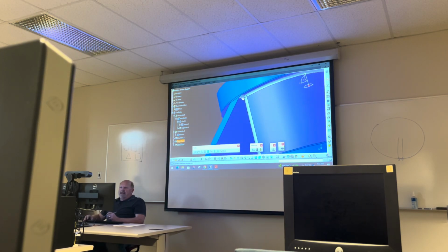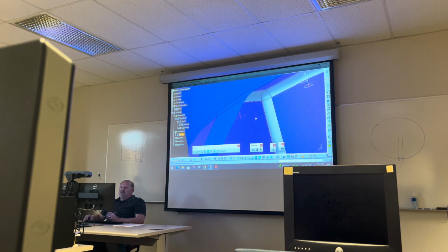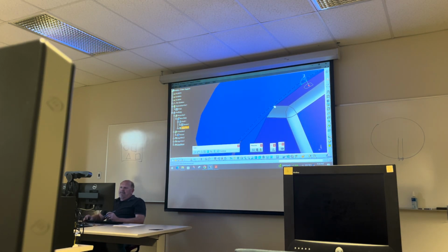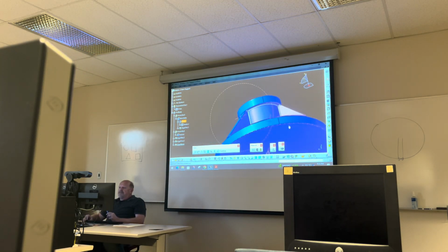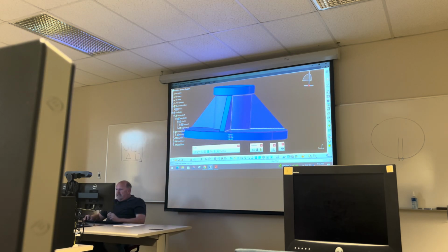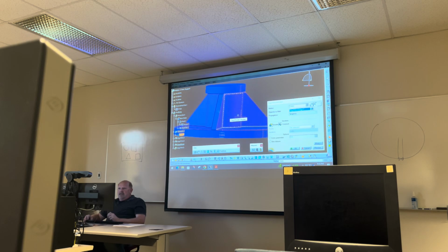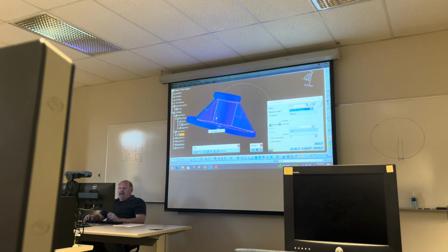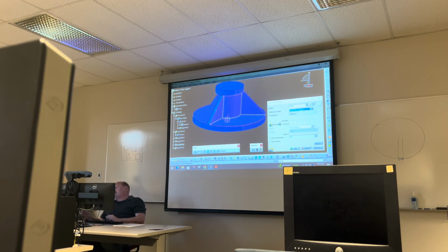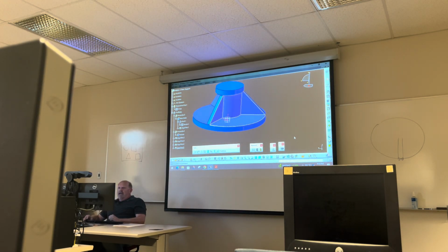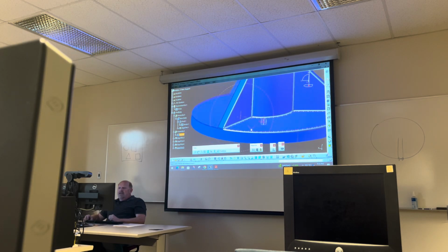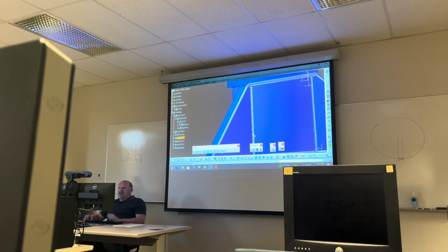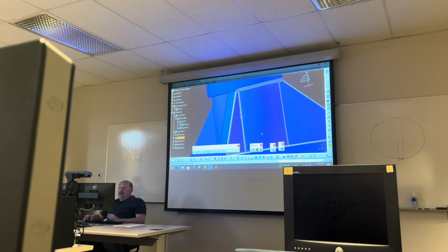But when I get up to the top, I've got to do something here, because if you look, there's the fillet at the top that was on the original base, or the part that you use the shaft command to revolve. So now if I go in here and I pick this edge, if you look at it, it says, oh, well, you are connected all the way around, and that's fine. That's what I'm looking for. If I get a gap in there, I know something's probably not right with the geometry. So I'm going to say okay, and sure enough, it ties everything together because it looks at the faces versus the edge blends that are there, and it completes the fillet all the way around that racetrack.